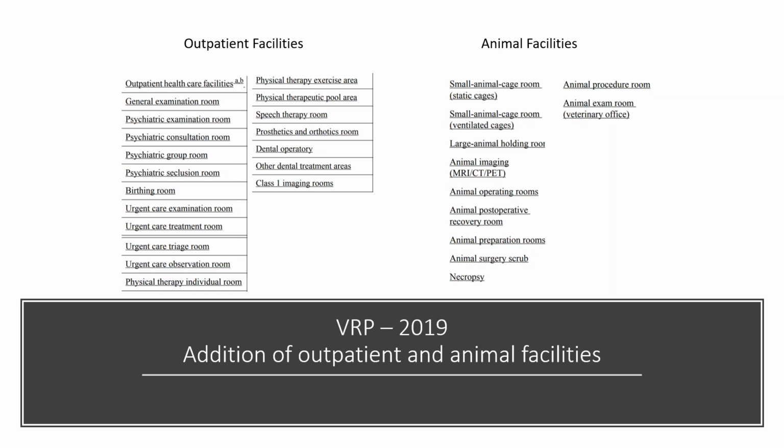So you go to the IMC or UMC. The IMC and UMC reference ASHRAE Standard 62.1. ASHRAE Standard 62.1 references ASHRAE 170, which is the healthcare standard. And ASHRAE 170 references ASHRAE Standard 62.1. So it was a cyclic reference, and no one owned these spaces, and it was always a point of contention. What should we do about these spaces? So now finally they found a home, which is ASHRAE Standard 62.1.